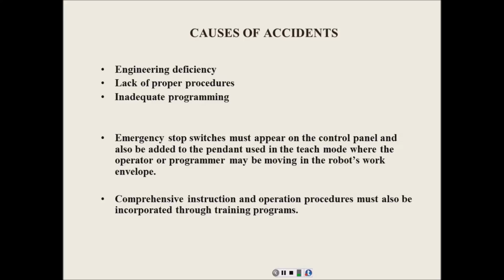You'll understand that. And of course, most of the accidents in robots occur during the teaching operation, teaching and maintenance. And usually with maintenance, guys fall off stuff. But with teaching, people will be in there with the work cell and not be cognizant of things that are around them, right? You understand? And something will happen. They'll stick their hands in there and try to move stuff around while the robot's in motion. And the robot has no idea that your hand is there. The operator does. But humans don't respond as fast as they think, right? Unfortunately.